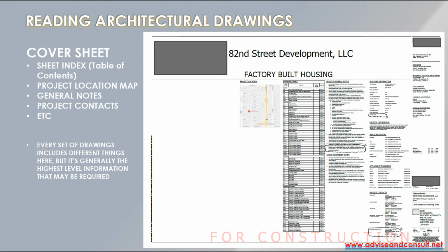the drawing set for that building. And what I want to do is highlight specific elements as we go through here so that you can see how to move through a set. Because the basic approach to understanding architectural drawings is that you go from the macro to the most micro. And the way you navigate through that set is to start at the largest scale and then to move your way down to smaller and smaller scale details.